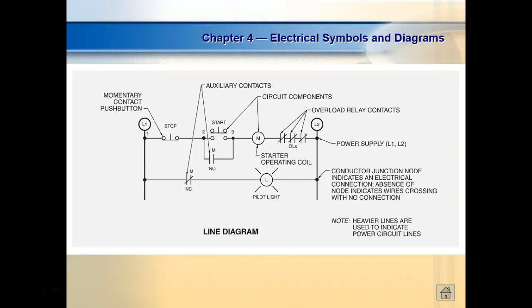So a lot of your small motors don't have external overloads on them. They have internal overloads. You'll see it, and it's a little thermal switch. And this gets dangerous because this came off an HVAC system, and your blower starts running. The electrician goes out there, tears the HVAC system apart and gets his arms in there and doesn't disconnect power, and then these automatically reset, and he's got his hand inside the blower, right, and all of a sudden it does what? Cuts on. But most of your small motors have internal overloads, especially just about every one that you've got in your house. So pass this around again.